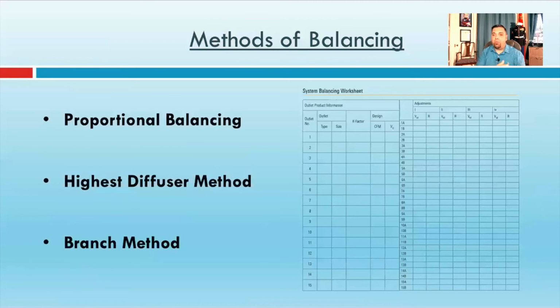Okay, so you plug it into the fan law, and if you are to get those pressures correct, so you start with the biggest ones and go down the line to the smallest ones, if you get the pressures correct, when you then go back and measure, you should have the correct volume of air at those takeoffs, as long as you don't have a lot of duct leakage in those runs, right? So those are the 3 methods.